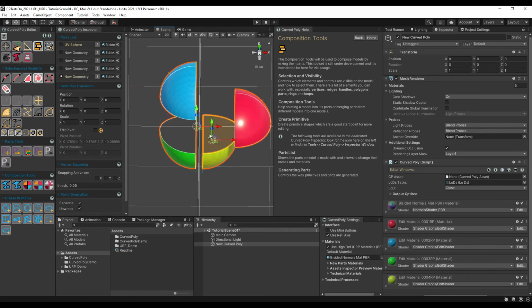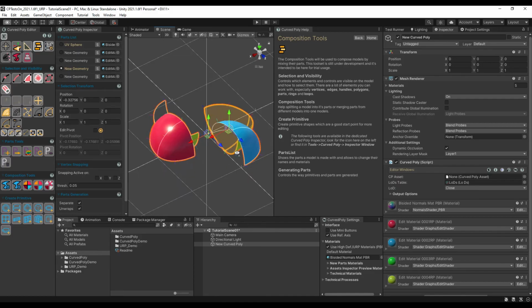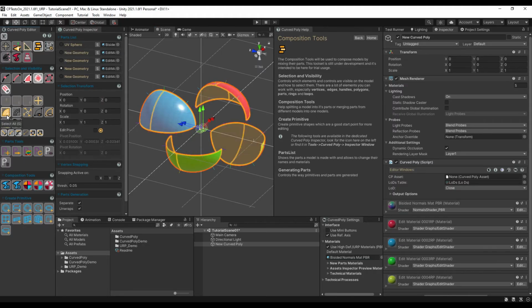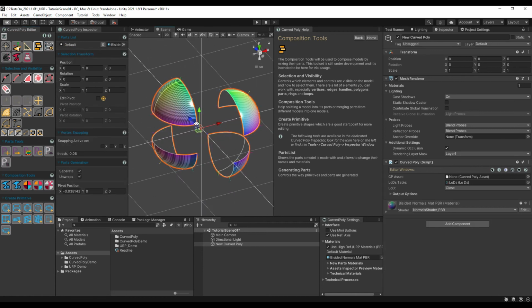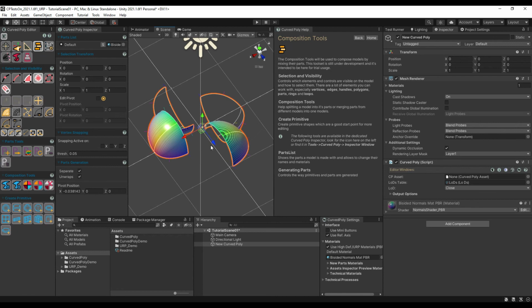A further step to consider is to reset the part by returning all the polygons to a single default part. To do this, just select all the elements that make up the model and do a reset of the parts. Once the parts have been reset, it is possible to reorganize the model into parts from scratch, and eventually to redesign the unwraps using the materials tools.